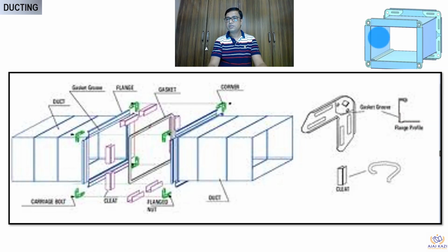Now it looks like this. This is the duct. It looks finished, but it has, as I said, a flange joint, and for the flange joint in the SMACNA standard, we now use these corner pieces which have a hole for nut bolting. So this is called a 4-bolt system, right? Now this is at the corner. This comes from the factory, which is the flange. So in this flange we insert this connector and we complete the duct like this.